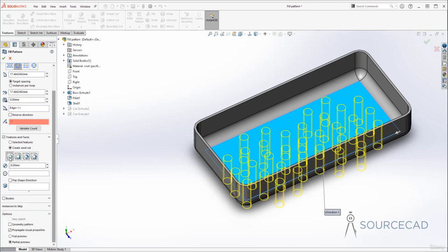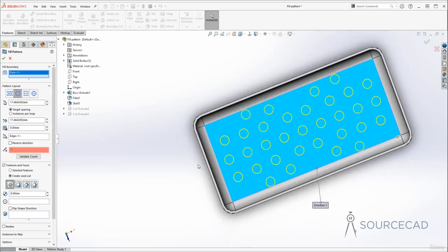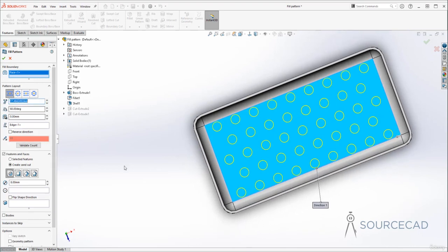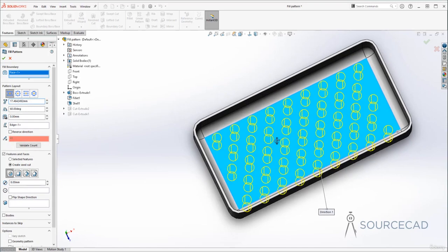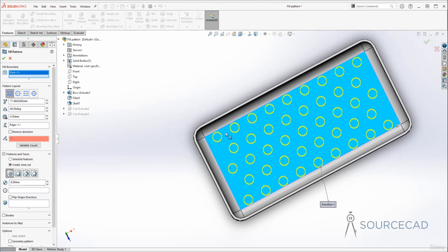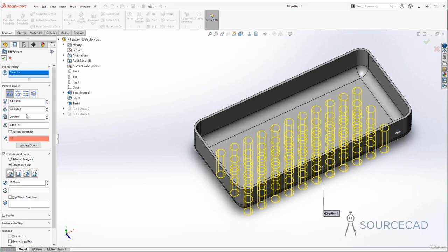So also, if you select any of these seeds, you still have the option of selecting the pattern type from here. So in this case, we are getting the circular pattern. You can change it to this. Well, the first one, and the perforation one, and then we have the circular, and then this usual linear pattern, and so on. So you can choose the type of pattern. Maybe we'll select the perforation pattern. There we are, and we can decrease the gap here, so it's kind of huge. So I'll just make it maybe 14. All right, so there we are, it's 14 now, and with that you can just click OK, and that's the pattern.